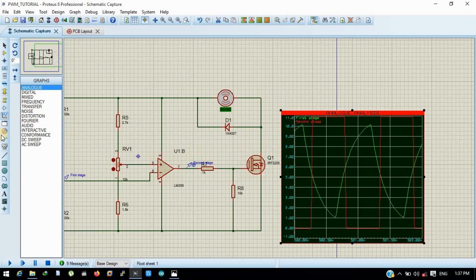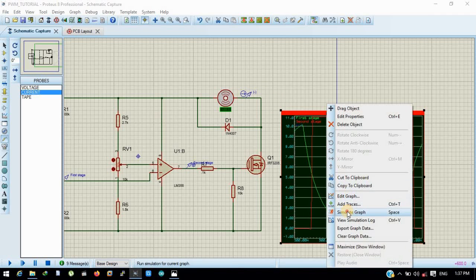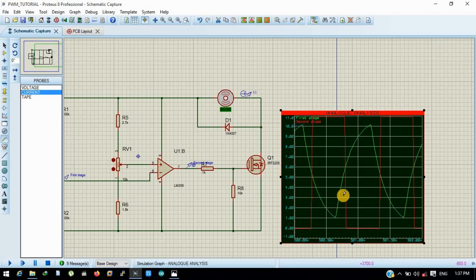Now we need to add one more trace, but we will measure the motor current. A click on this probe and dragging the name to the graph will add the trace automatically. Now we should see 3 plots.